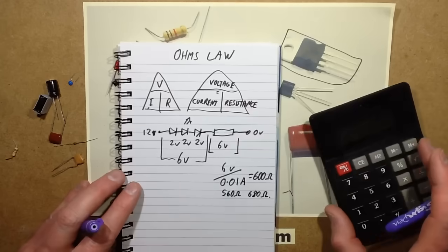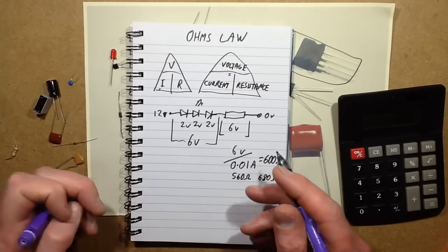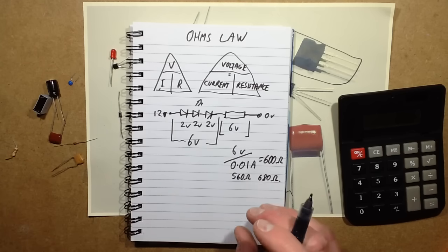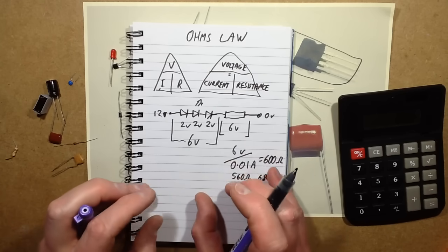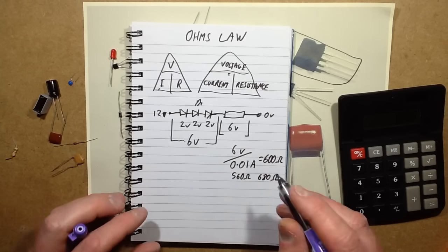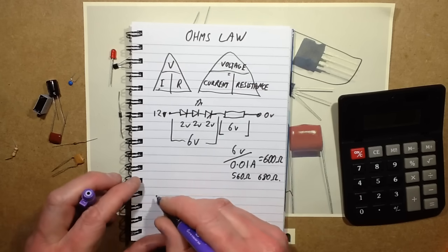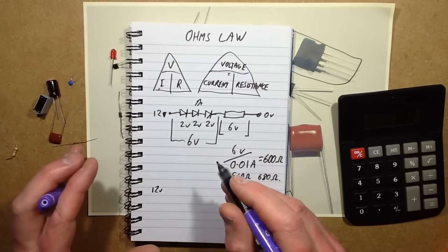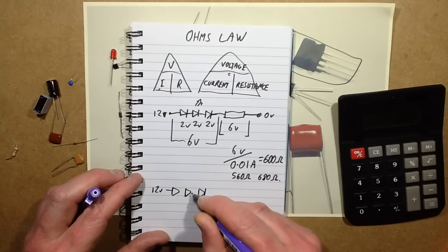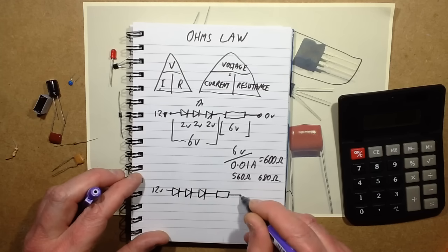And the other way this formula can be used is if you are trying to measure how much current is flowing through some existing LEDs, say you're measuring some LED tape. Putting an ammeter in series with it actually skews the reading a bit, because the voltage drop across the resistor in series with LEDs is so low. So say for instance you've got a 12 volt supply feeding more LEDs, but you don't know the voltage across the LEDs, and you don't know the current through them, but there's a resistor and you do know the value of the resistor.